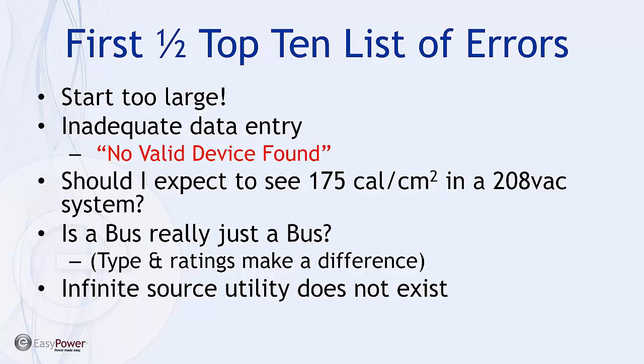So there you want to make sure you get as accurately as possible information from the utility company, and if you have to make assumptions to generate whatever data you use, then the way to guard band that is to actually use a number bracketed with numbers that are less than what you receive from the utility. Again, lower numbers generally refer to longer tripping times, which would reflect in higher incident energy.